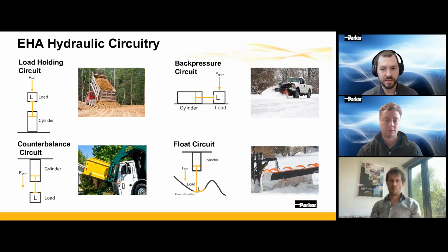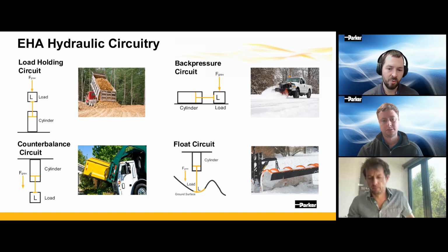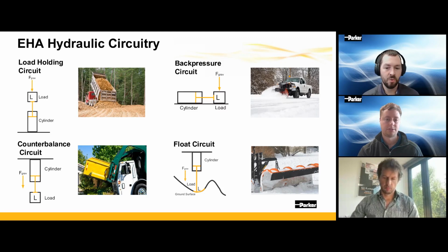And float circuits. So that is something like if you've got a snowplow blade or some type of ground engaging device where you might want to load hold in a retracted or extended position and then unlatch, per se, the device where you can follow the ground conditions like a road or a surface in the soil. Float circuits allow you to do that.